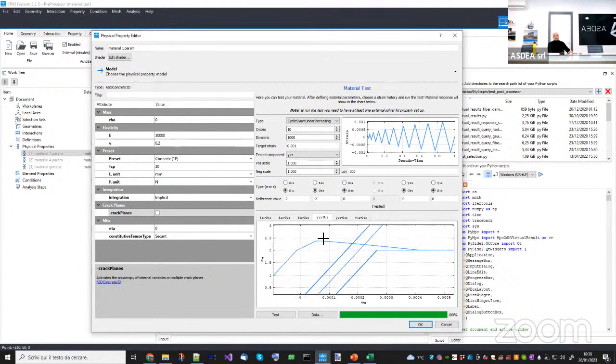So I will start with the same level of damage. Graphically, it means that if I have a specimen like this, and I'm loading in this direction and I develop a diagonal crack here that was giving the first softening. When I load in the other direction, I don't have any crack, but I will find the same damage. So what I would expect instead is to load in the other direction and go back to the initial strength and then develop another crack in this direction here, okay?